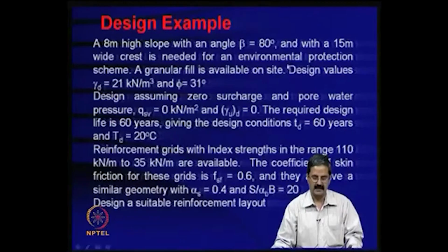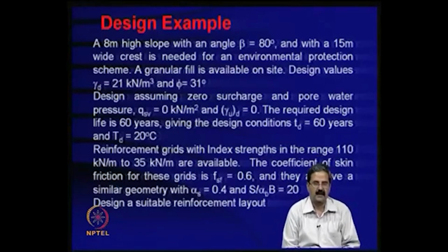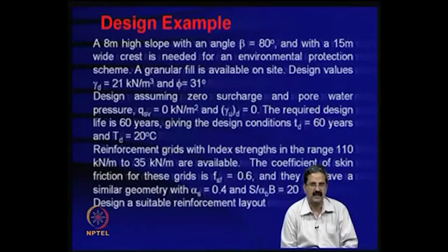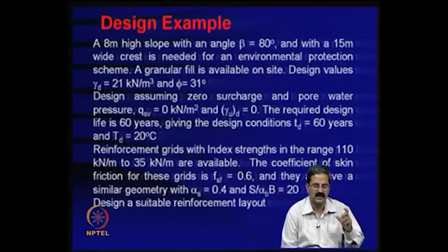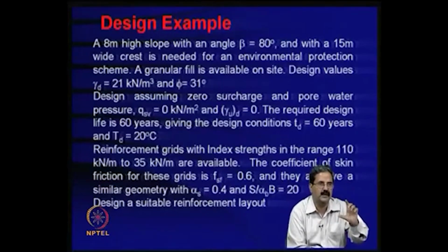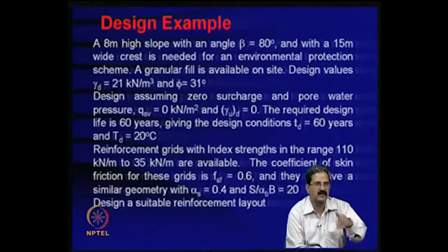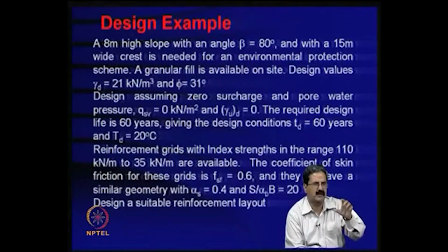So, there is 8 meters that you have, suppose somebody says that I have a 20 kPa load, then the way we get the equivalent height is that you have to consider that extra 20 kPa load and also the unit weight of that soil. So, once you do that, you will get that equivalent height, it is nothing but Q, which is 20 kPa, Q divided by the bulk density, say for example 18, 20 by 18 will give you the extra height, say 1.1 or whatever.